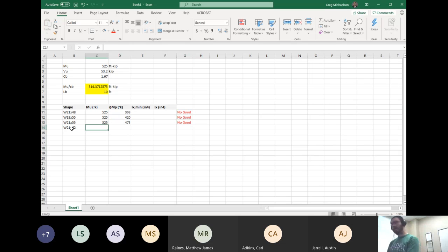All right. Now, Mr. Marone, MU is 525. What about phi MP for the W21 by 62? I think that's a bold one as well. 540. Okay. Now, here's the kicker. Is this a good section or not? Well, the way that I would say it is this. I would say it's worth considering. In other words, we don't know if it's good, but we know that phi MP is larger, so it's worth doing the math on.